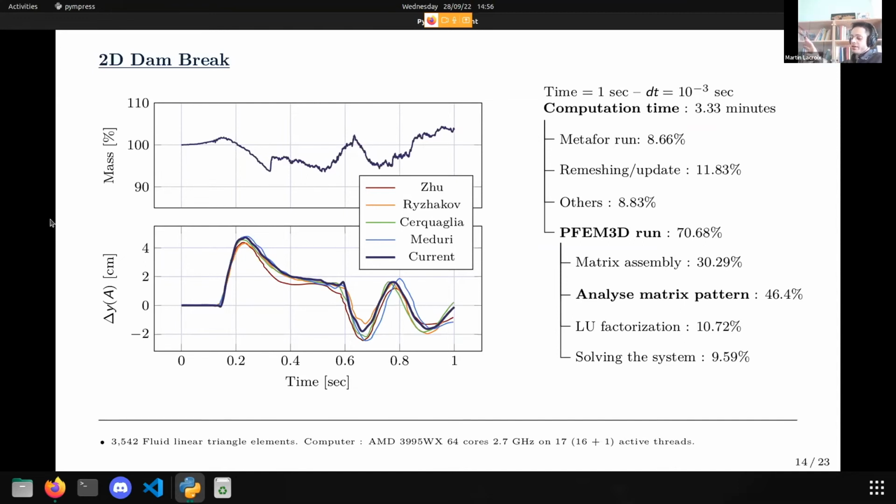Something just to add that can be useful to reduce this mass change is to refine. For instance, you can use a mesh where the characteristic size of the elements depends on the location. If you are closer to the free surface, you may use elements that are much smaller than the elements created in the middle of the fluid. And if your free surface is much more refined, of course, all the problems of detachment and reattachment are smaller. They are not zero, of course. You will still gain or lose mass, but on a smaller scale.